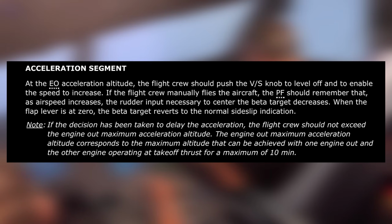Maintain the thrust levers at the current position. A common error is to command TOGA at this point, which will result in an undue activation of the go-around phase.